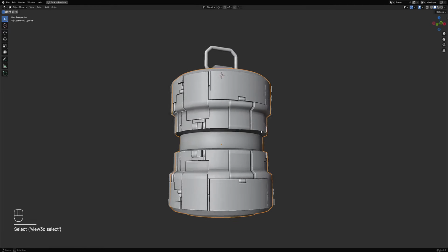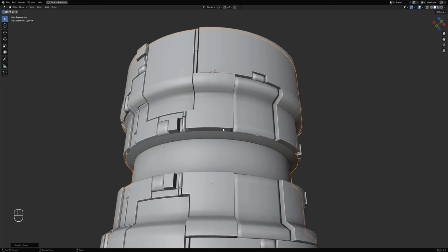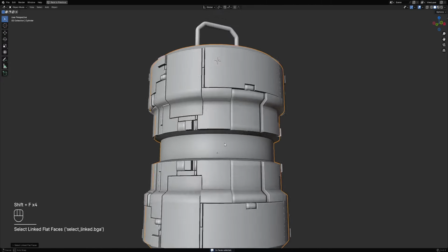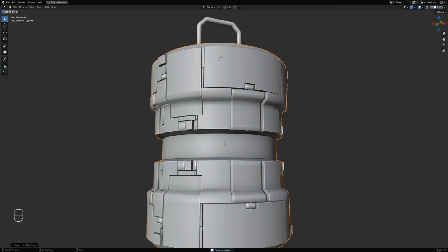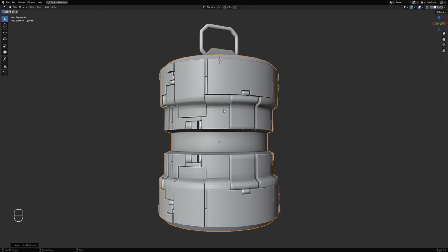Okay, let's select the base mesh and Control Shift A to select. You can see that the red, it previewed the selection using the color red. That means that those faces are deselected. So Shift F, F, wait a minute. Okay, I also need this to be asymmetrical. Let's see. So Alt click on the objects, Alt right click, and it will show you all the objects underneath